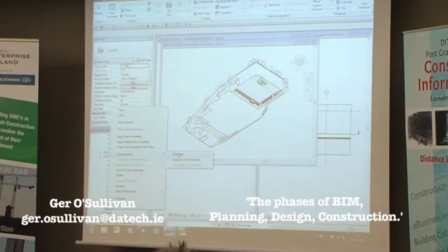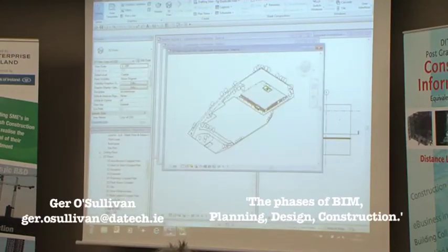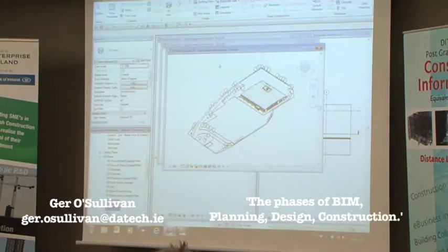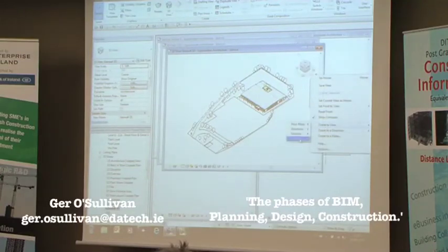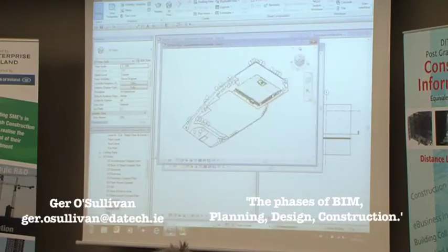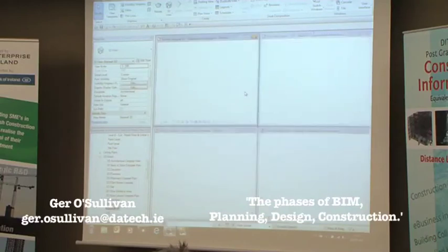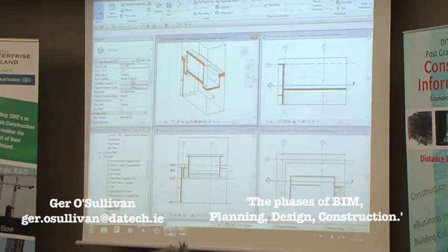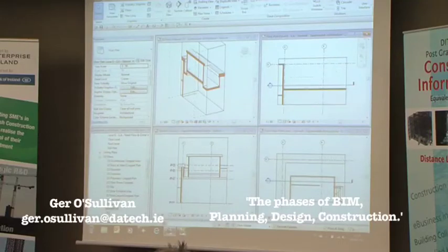Again, you're not doubling up on the information, we're just making a copy of the view, and we'll rename that to stairwell 3D, and we'll crop it down very quickly to the actual stairs itself, something like that. So you're getting the idea how easy it is to manipulate the geometry, and that's now what we're seeing in 3D. So there are my 3-4 views ready for geometry to be added to them.